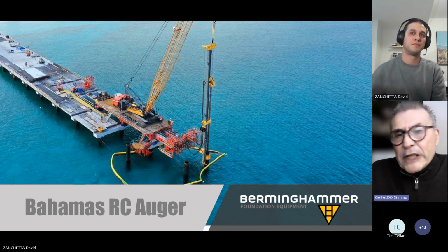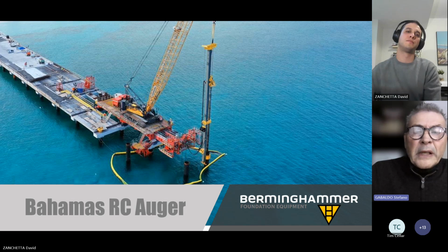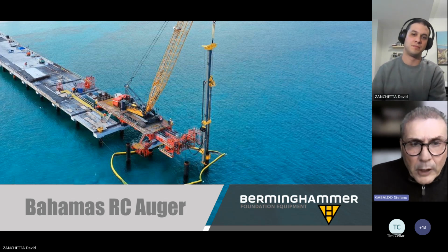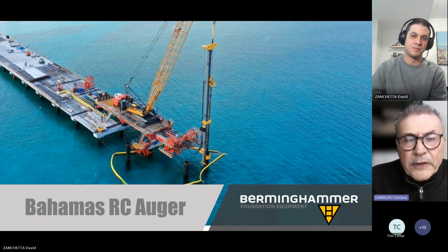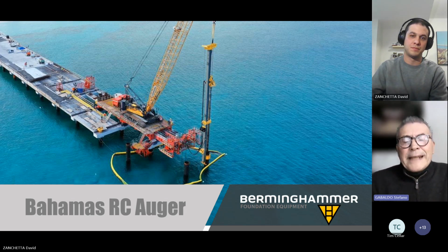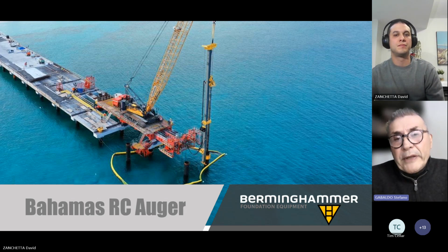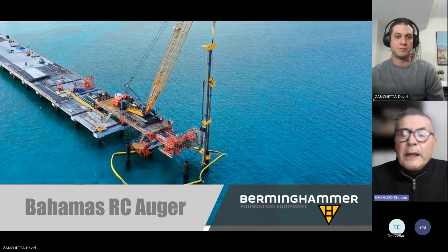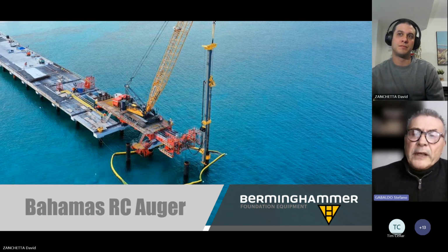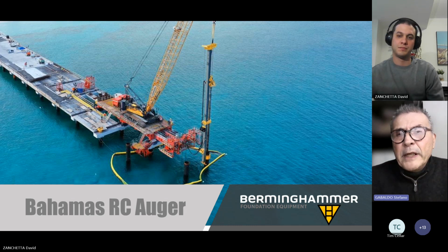If that ability is not enough to fulfill the full amount of torque that we put on the drill, then if you see at the very bottom, there is a little yellow bar at the very bottom of the lead that basically goes inside a template fixture in order to increase these torque capabilities. So our lead typically have both. We typically like to rely on the stiffness of the pile. If that is not enough, then we just engage the template in order to react against this torque.